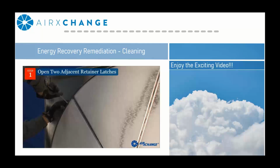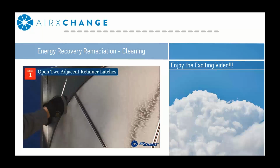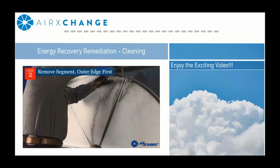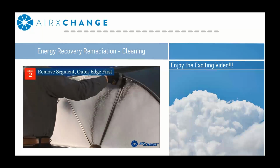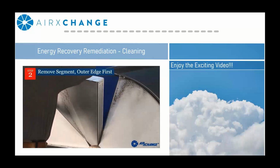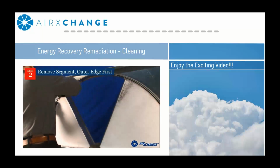Okay, so to quickly demonstrate that process, I've had some luck with this video, so hopefully it works for you all. This is how the segments get removed. The heat transfer media is held in through a series of clips in the unit itself. You just unlatch those clips, and the energy transfer segment gets removed. You put it aside and repeat it for all the subsequent segments.